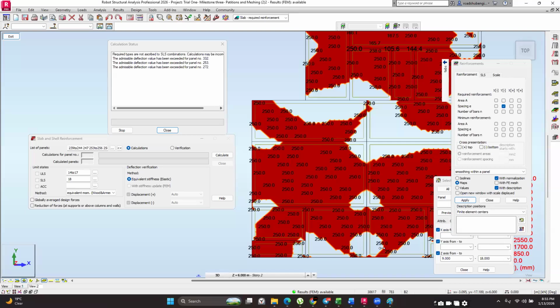If you go above bar diameter 12 for your slabs, your structure is going to be too expensive, and it's going to look very shoddy. If you give someone a detail for a slab using T16 bars, that is quite rare, especially for normal projects.